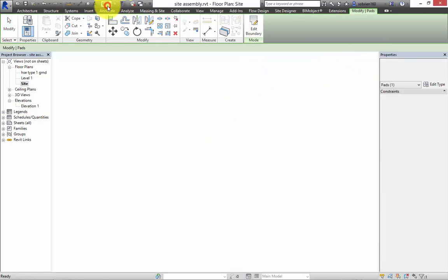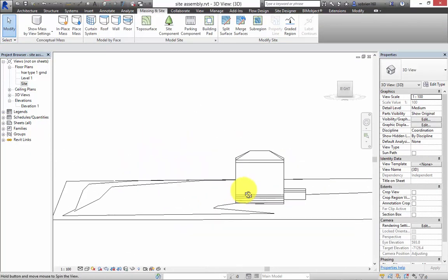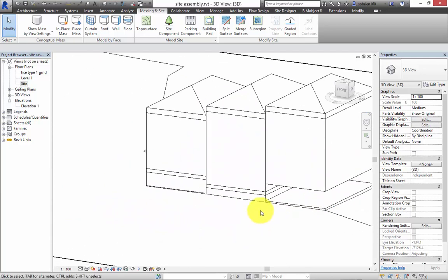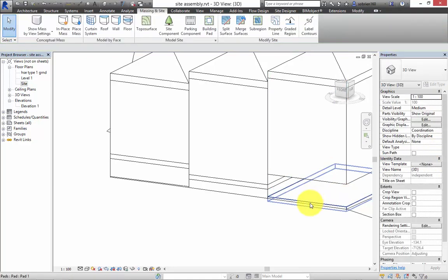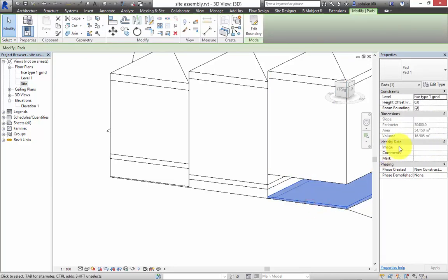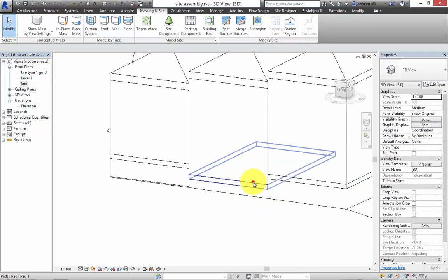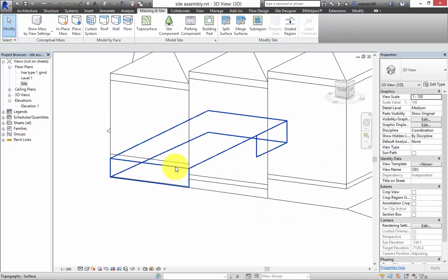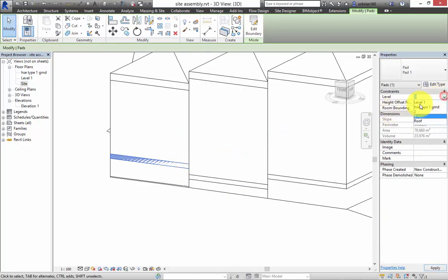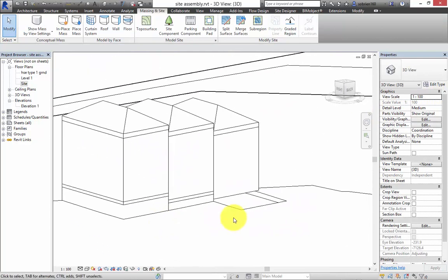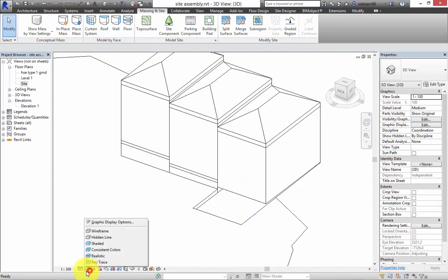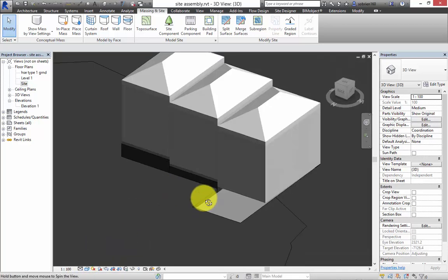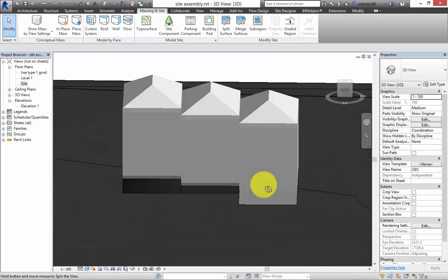So when you're finished, you have something like that, where the building pad, I've actually done it backwards. This one should be on level 3. You can always come back and modify it afterwards. This one should be on 2. That one's fine. This one should be on level 1. So it builds the site up around it, or excavates the site out underneath it. So if I just turn on the shaded view here, you can see how that does it.